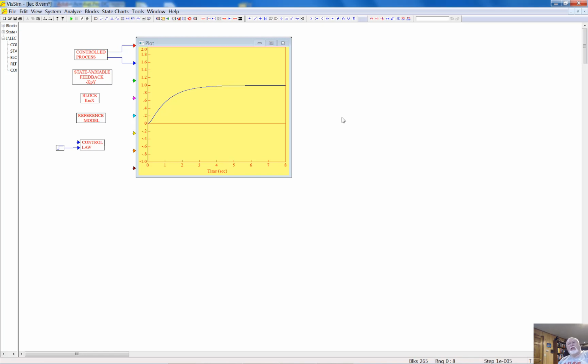I would say that this numerical example shows you the main issues in model reference design. First of all, you have to stabilize the control plant. And when you stabilize the control plant, your only goal is to achieve stability. The specific eigenvalues of the closed-loop fundamental matrix are not that important, but they should be in the left-hand side of the complex plane.